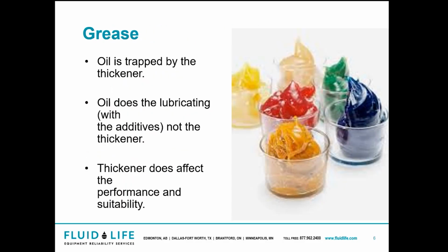So grease is just oil trapped by a thickener. Oil does the lubricating with the assistance of the additives. The thickener, however, does affect the performance and suitability of the grease for applications. Obviously, you're going to need a very different grease for something like an electric motor bearing as opposed to pins and bushings on an excavator, or on a pump, anything like that. Even the spider joint on a flywheel or a drive shaft.